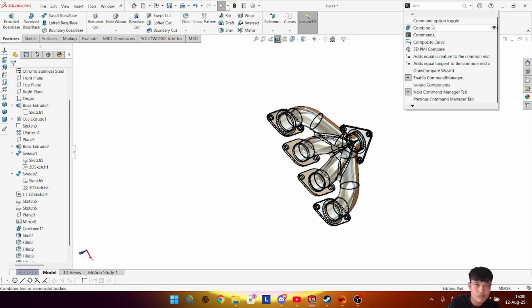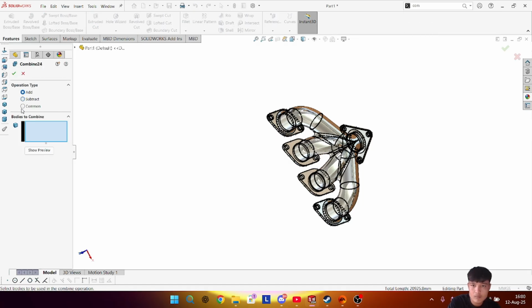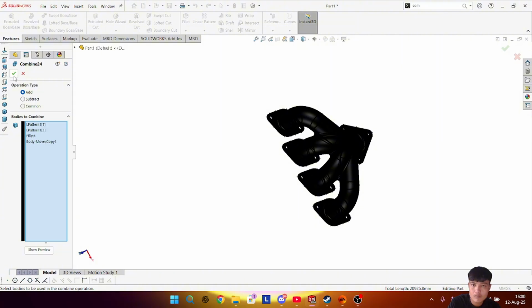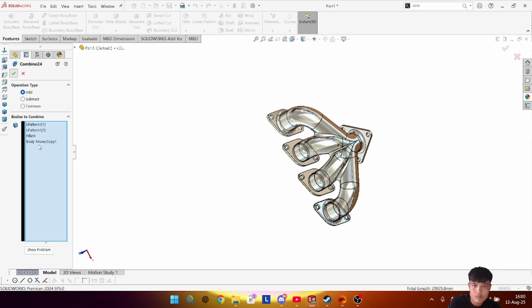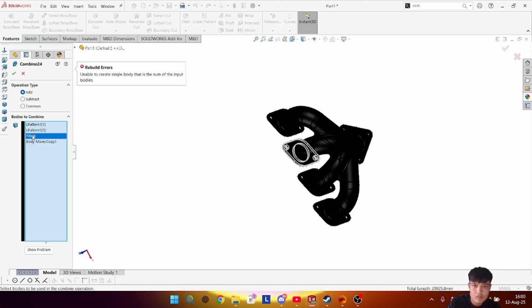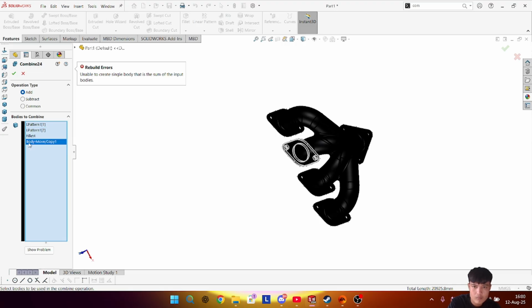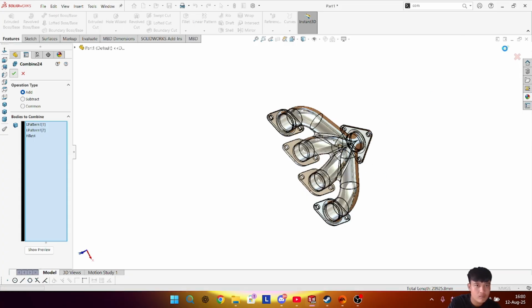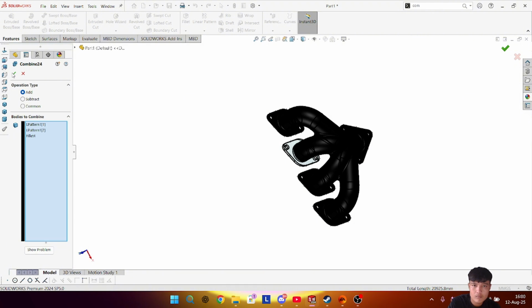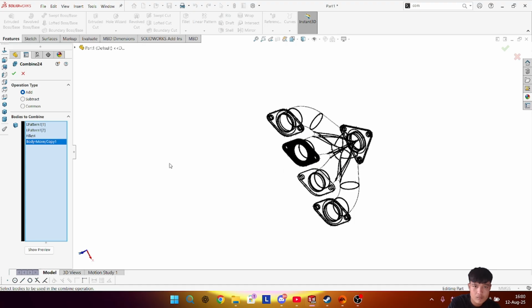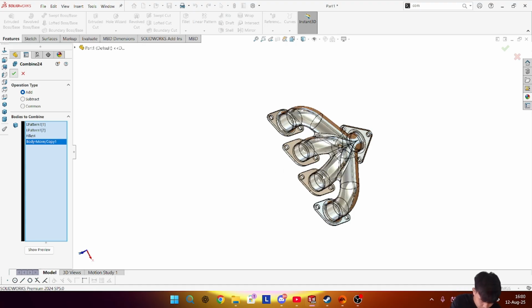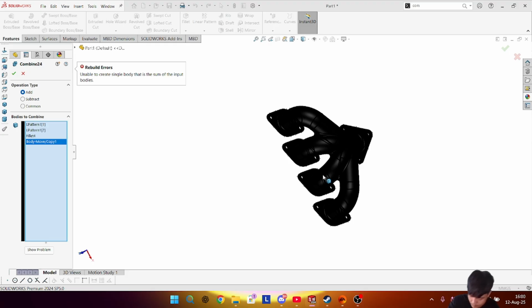Now choose circle. Define one, the same six circles and one circle in the middle. Now select all outer circles and make a relation. Keep your relation inside, equal. Okay. Now let's define this one, outer 30 millimeter.